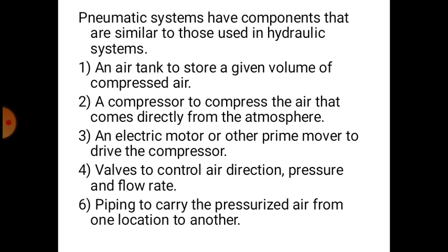So pneumatic system has components that are similar to those used in hydraulic system: an air tank to store the given volume of compressed air, a compressor to compress the air that comes directly from the atmosphere, an electric motor or other prime mover to drive the compressor, valves to control air direction, pressure and flow rate, and piping to carry the pressurized air from one location to another. These are the components which are used in the pneumatic system.